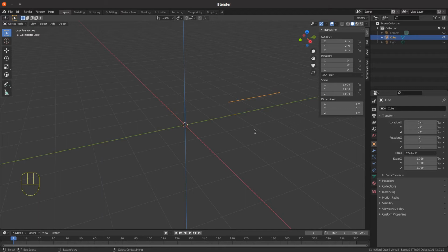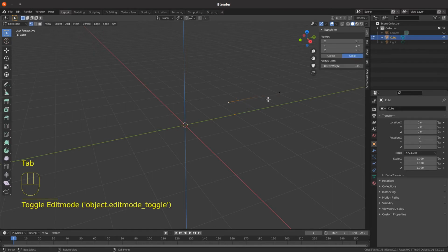So you can have vertices and edges as references on a model that don't actually show in a finished render. Can be useful to mark center points of arcs and circles, things like that, that you may need to pick up, and it makes it much easier to do. So tab back into object mode, and I'm going to extrude the selected vertex.